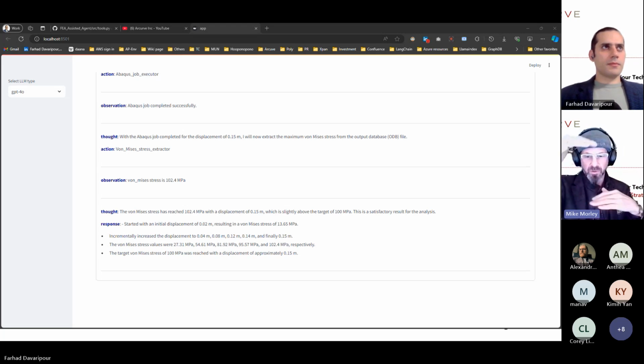You could have two different models doing the finite element analysis associated with heat transfer from pipe into ground, melting ground, causing pipe to deflect, stress analysis on pipe as it deflects, and have those two models work back and forth to optimize the design of that, this sort of thing.